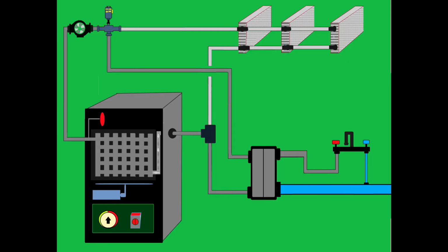You have another choice. You can go with an instant heating like the Combi boilers. What you'll see here, you have the 3 heat exchangers on the top, you have the 2-way valve, and also you have the plate heat exchanger. But this boiler should be strong enough to heat the water instantly. So the heating agent, which goes out from the boiler through the pump into the 2-way valve, is directed into the plate heat exchanger, which you will see on the right hand side at the bottom,